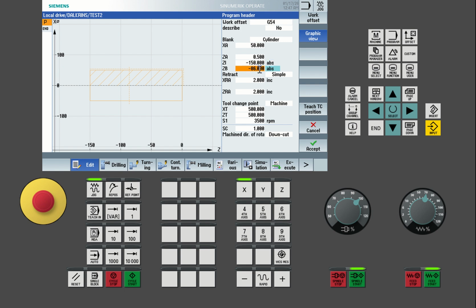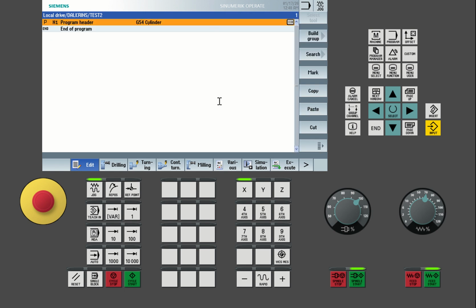Then this is the amount for the area that will be cut, and then here incremental for safety along X, and then incremental safety along Z, and then here use the machine. You click on teach so that you can pick the values. Check here: for example, you can put 1 or 1.5, and then here down cut, then click accept. From here, that is for description of the material for facing.